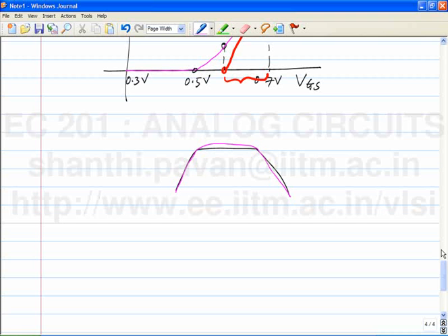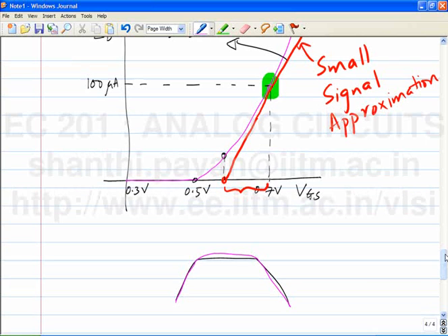It's much easier to compute things assuming everything is linear around the operating point. So even though these swing limits that we have calculated from the small signal parameters are not entirely accurate, they are very good approximations to the true swing.